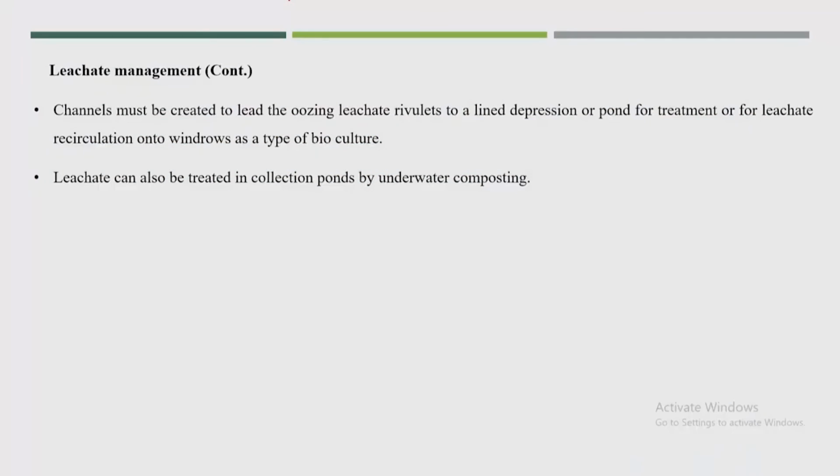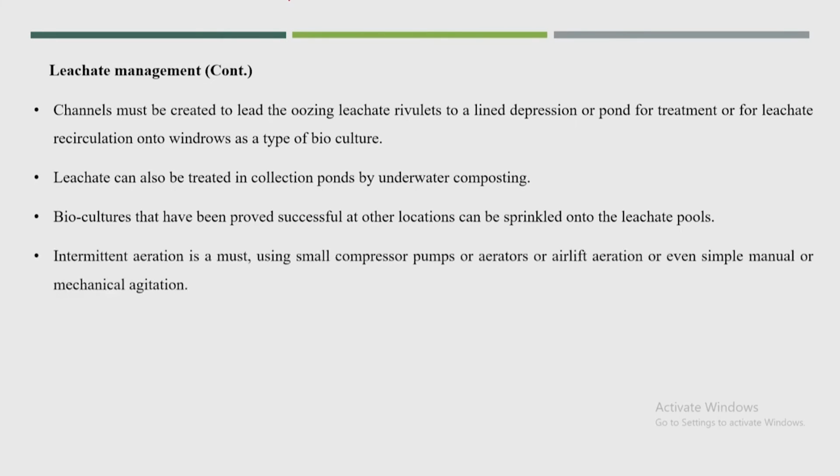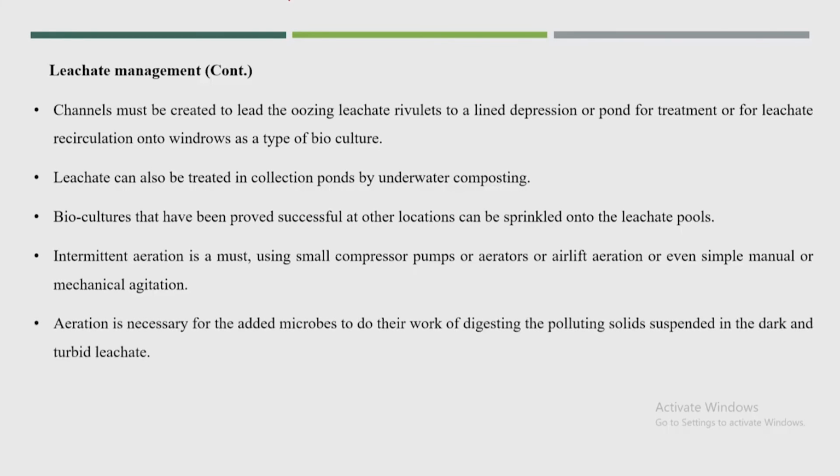Or leachate can also be treated in a collection pond by underwater composting, but I think this will be a somewhat costly process. And bioculture that has been proven successful at other locations can be sprinkled onto the leachate pool. Intermittent aeration will also be beneficial, and aeration is necessary for the added microbes to do their work of digesting the organic matter.